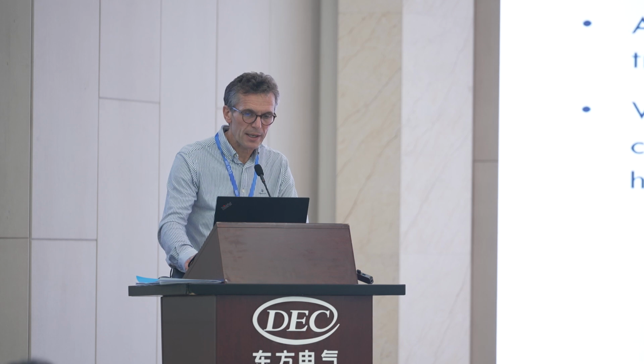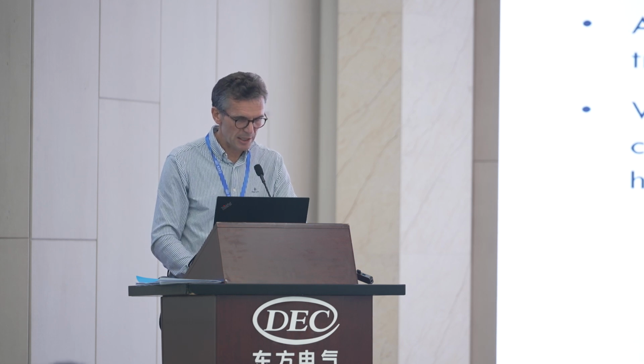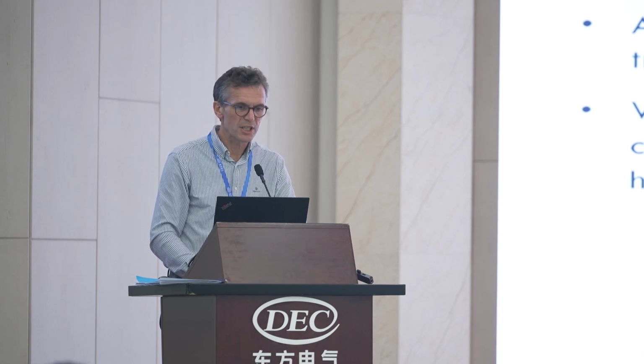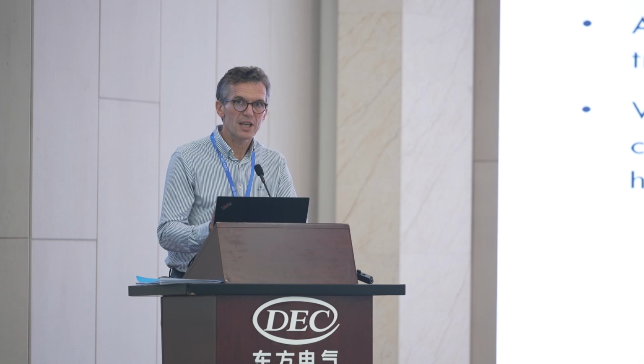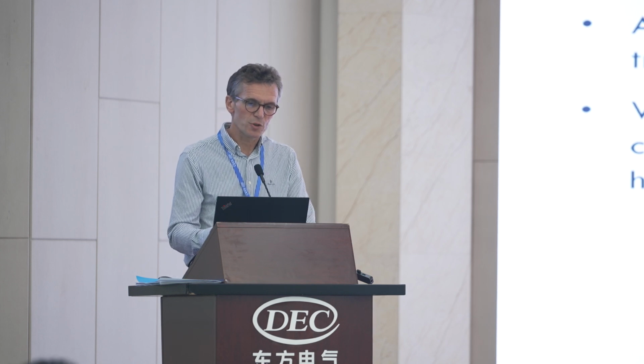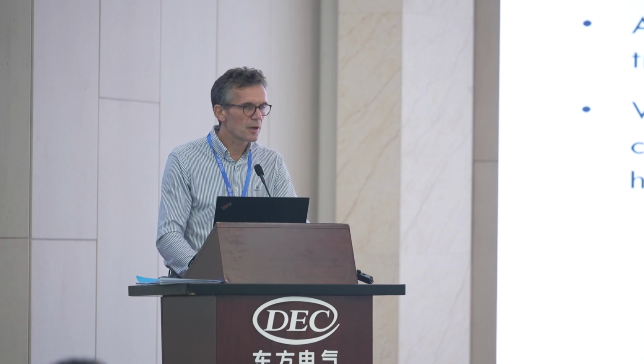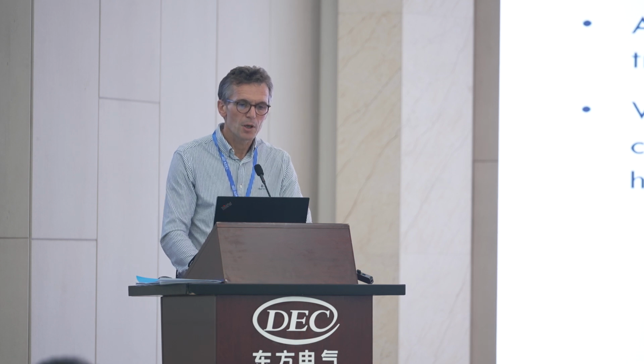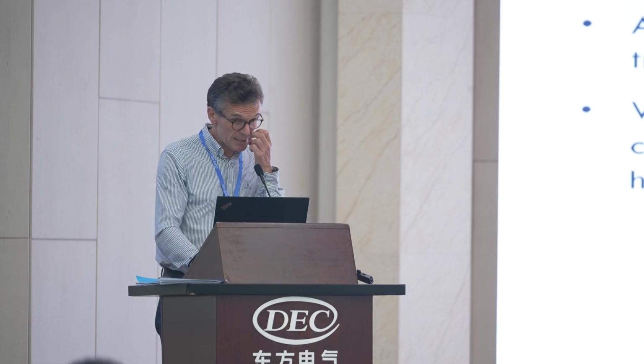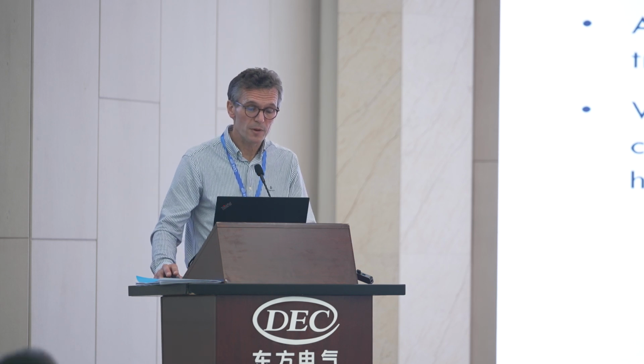Therefore, we went back and had a further look at this ilmenite T2, to find the reason for the problem with agglomeration. It was delivered dry, and the dry tests with methane were not exactly the same as for the other ilmenite. So by adding some steam, we observed no agglomeration anymore, and by doing this, we could solve that problem.